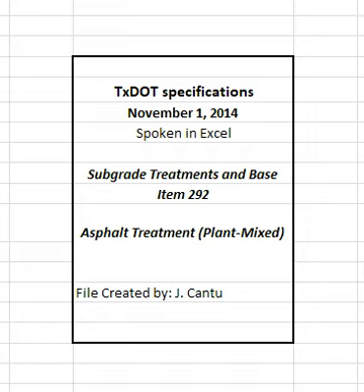The engineer may authorize hand finishing when the mixture is placed in a narrow strip along the edge of existing pavement, used to level small areas, or placed in small irregular areas where the use of a finishing machine is not practical.